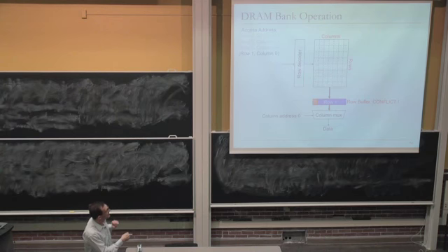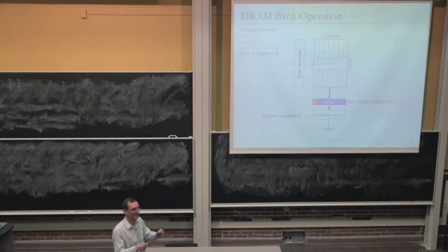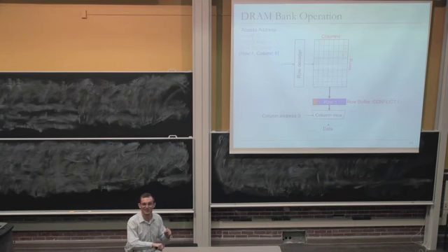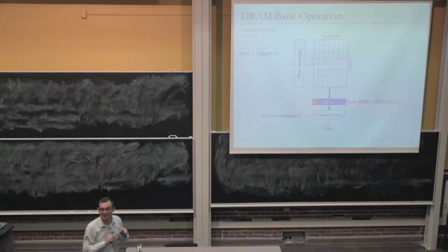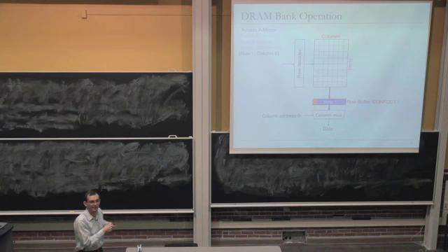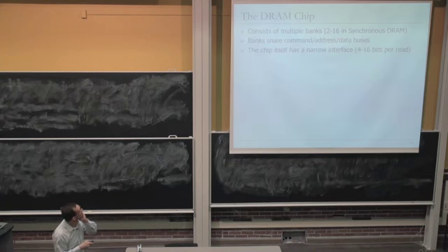And that's why existing DRAM controllers try to optimize the locality in the row buffer, such that when you open a row, you take the best advantage of it. If there are requests going to the same row, prioritize those requests. Which makes sense, right? That way you reduce the average latency, as well as maximize the bandwidth throughput you're getting from DRAM.